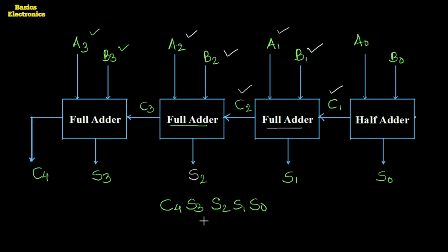If we have to construct the binary adder for more than 4 binary bit numbers, then we have to use one more full adder here, and instead of taking this C4 outside in the result, we add it as a third bit to the next full adder.